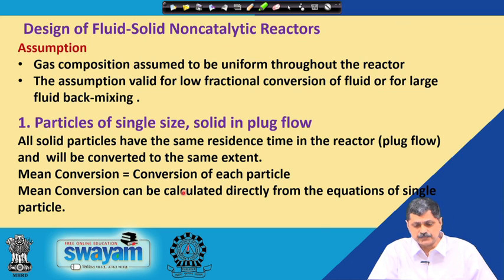In the design of fluid solid non-catalytic reactors, we will make one basic assumption, and that is the gas composition remains uniform throughout the reactor. This assumption is reasonably valid if the conversion with respect to the gas or fluid is small, or if the fluid back mixing is large. Now, we will take up three cases. The first case is the particle is of single size and the solid is in plug flow.